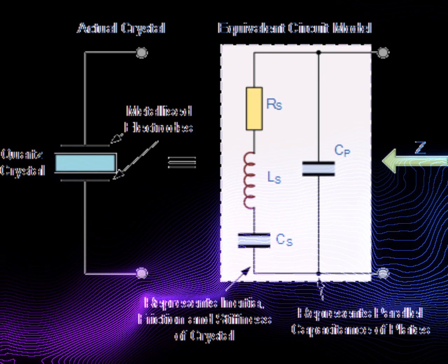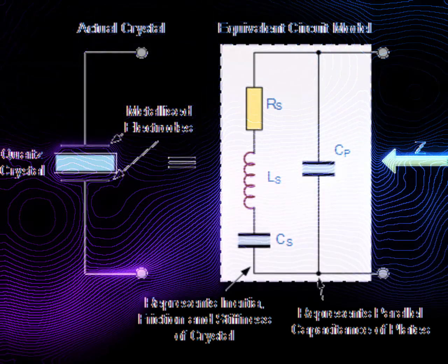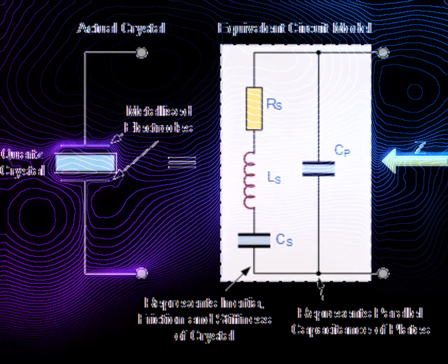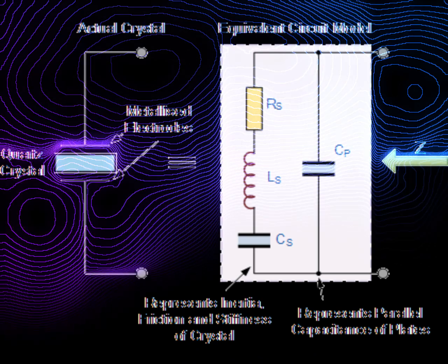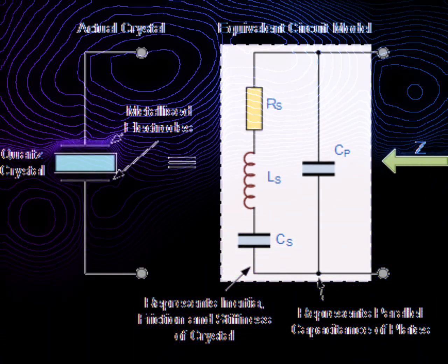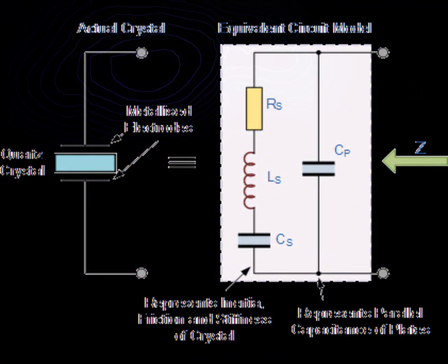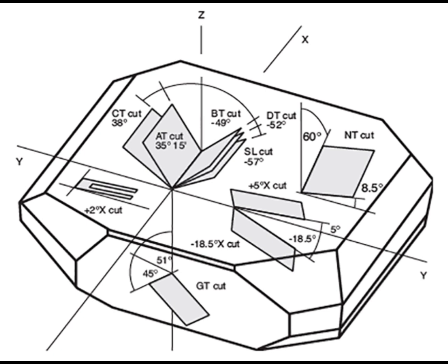Correct selection and sorting of cutting angle to ensure the desired frequency temperature stability. Careful crystal blank design that avoids undesired resonant modes. Appropriate blank polishing for lowest resonant losses. Cleaning of blank surface, electrode deposition, and hermetic encapsulation in a dry nitrogen atmosphere for long operating life. Production steps in more detail.